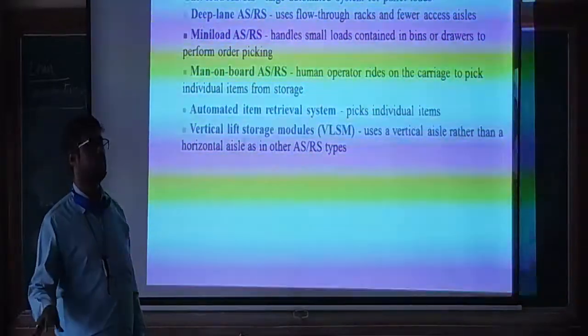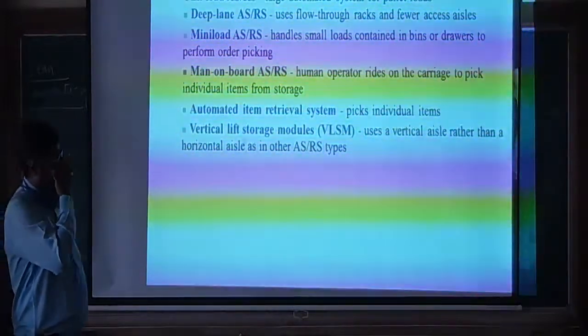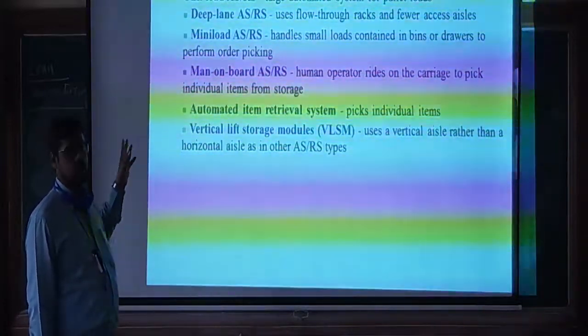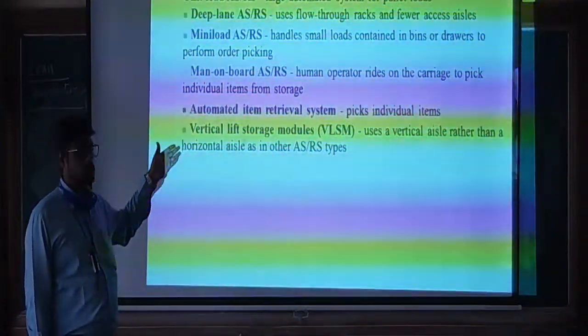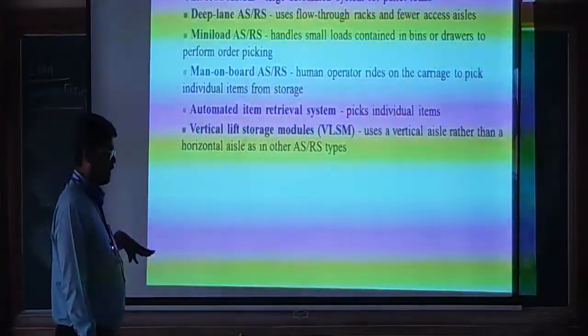Man on board ASRS involves a human operator. One operator is required to perform the particular operation of loading and unloading. The human operator rides on the carriage to pick individual items from the storage. So usually it is picking and dropping.